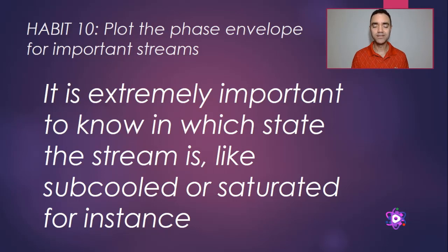Habit 10. Plot the phase envelope for important streams. It is extremely important to know in which stage the stream is, like subcooled or saturated, for instance. Every time that you are performing your process simulation, you want to know what is the behavior of your fluid, because that will help you to understand why the temperature is not increasing or why the temperature is not decreasing.